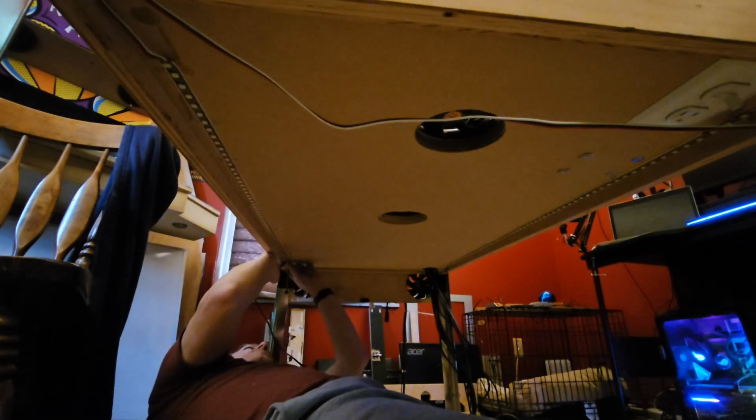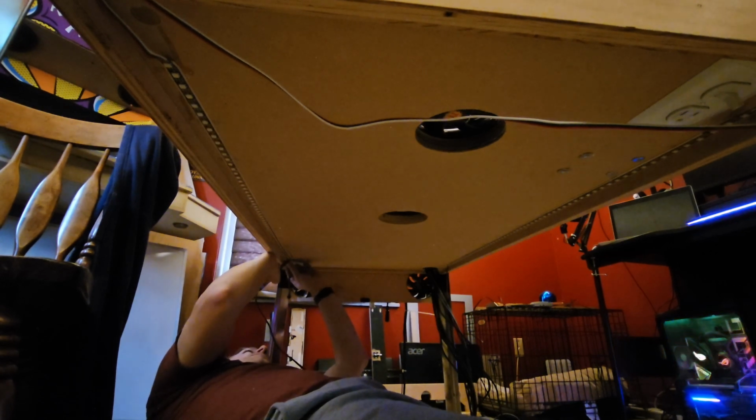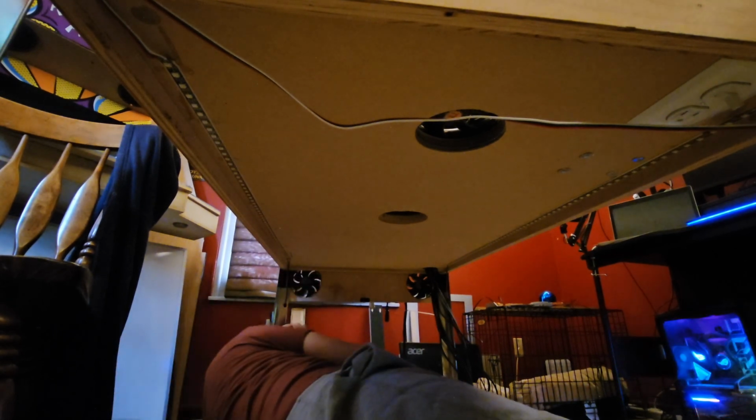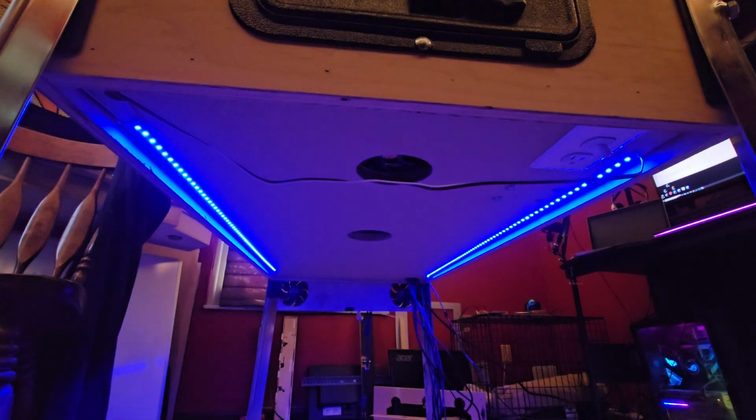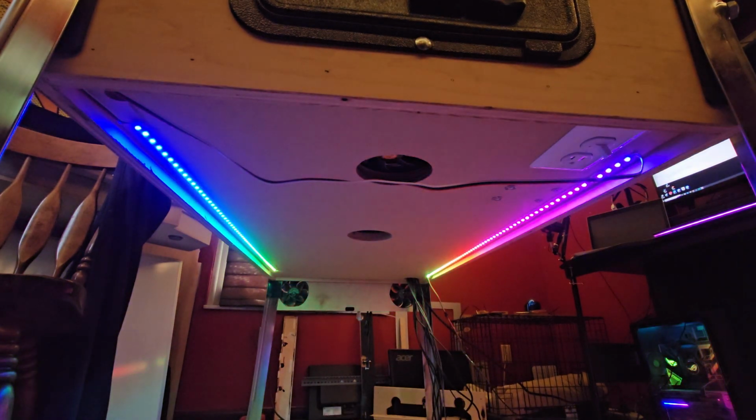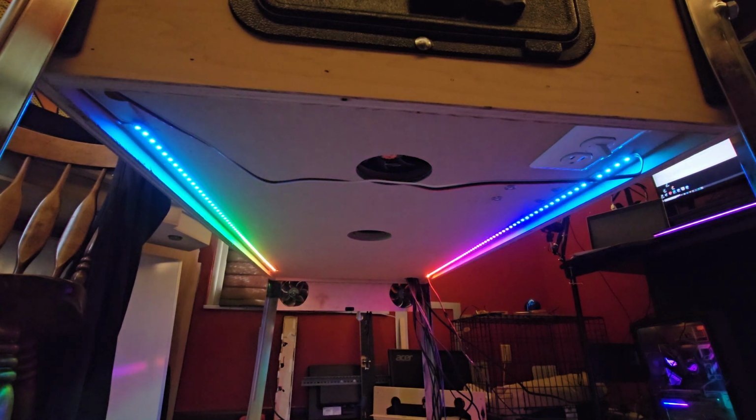And here I am adding on the male and the female ends. So the male end is on the right side, which is where pixel number 1 is. The female is on the tail end side. I don't know if I'll ever hook anything else up over on this side, but if I do, it's there and it's available and ready to go. I will end up adding some wire clips to the front end there so that it's not dangling down eventually in the future. But for now, I'm just going to leave those there.